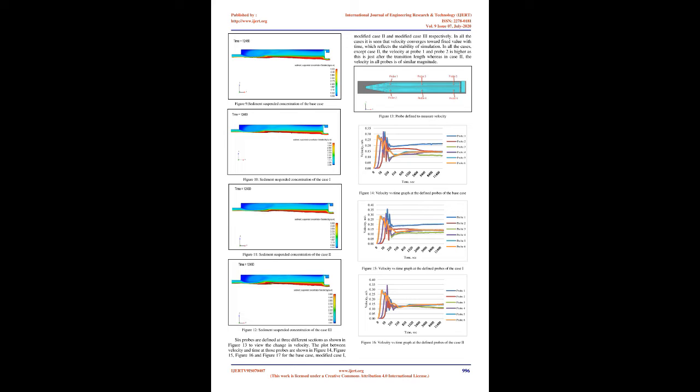D. Physical model. The physical hydraulic model test of BHP was conducted at the Irrigation and Power Research Institute, IPRI, Amritsar, Punjab, India. The desilting basin model was constructed to a geometrical scale of 1:12, which includes the feeder tunnel, desilting basin, and sediment flushing channel. The model was run with sediment load at intake as 2000 ppm for 1 hour, 3.46 hours in prototype. The sediment sample deposited in different sections of the settling basin was collected and the efficiency of the basin was obtained.